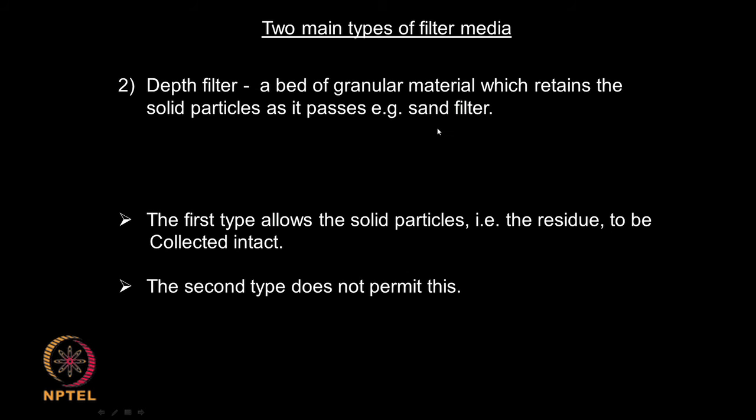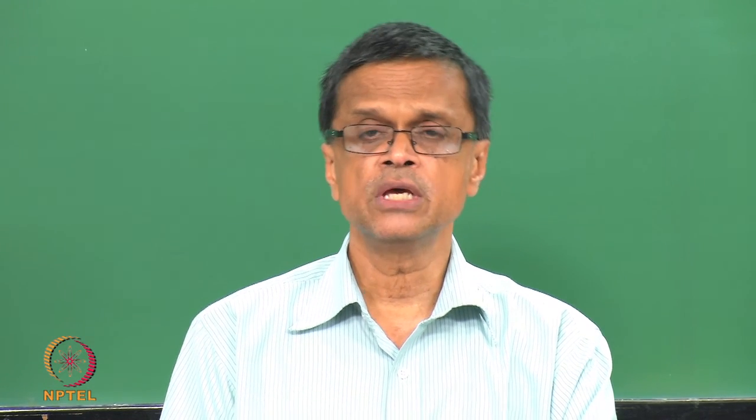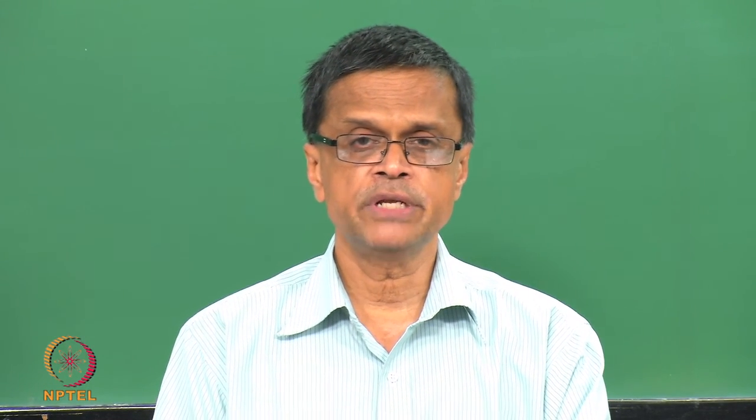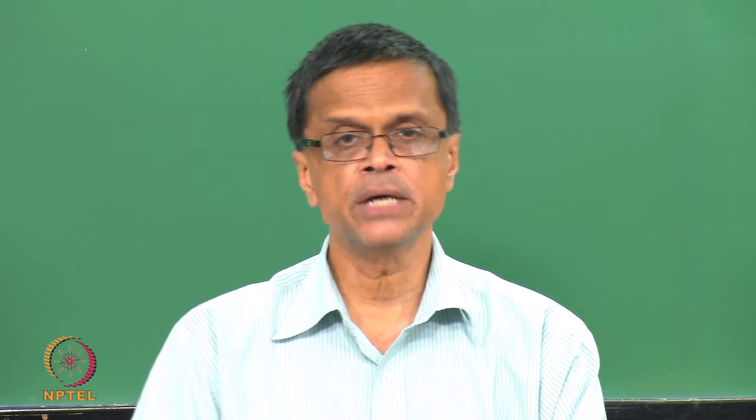So, the sand filter is like a bed of sand where the liquid flows through and the solids get trapped by the sand, especially in water treatment. Okay. This is a very simple setup, a very cheap setup. Rainwater harvesting uses a sand filter. The sand just traps the solids that are flowing through, and generally this is used if the concentration of solids is very low, whereas the first method is used if the concentration of solids is much higher.